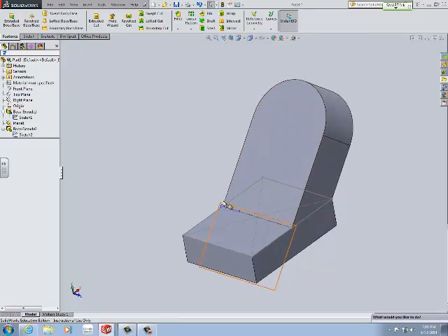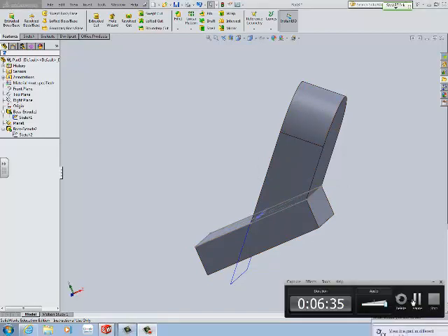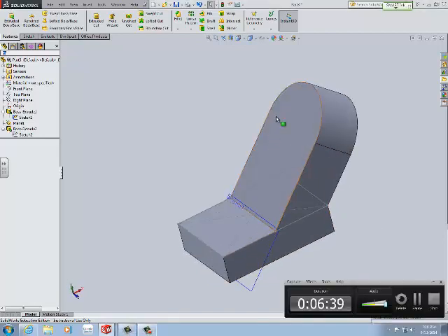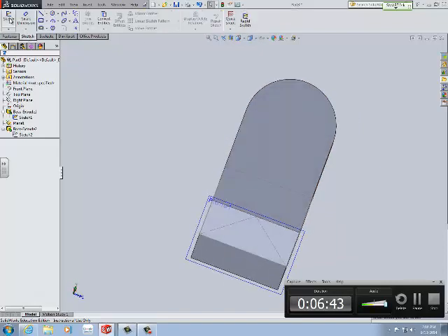So again, what I did is I created this part here, arc and square. Our next step will be to go to sketch, sketching on that same face of the cylinder we just created. Next is to center our circle at the center of the existing cylinder. What we can do next is actually with the diameter of 26. So we go back to sketch. Yes, we start a sketch. It's going all the way through.